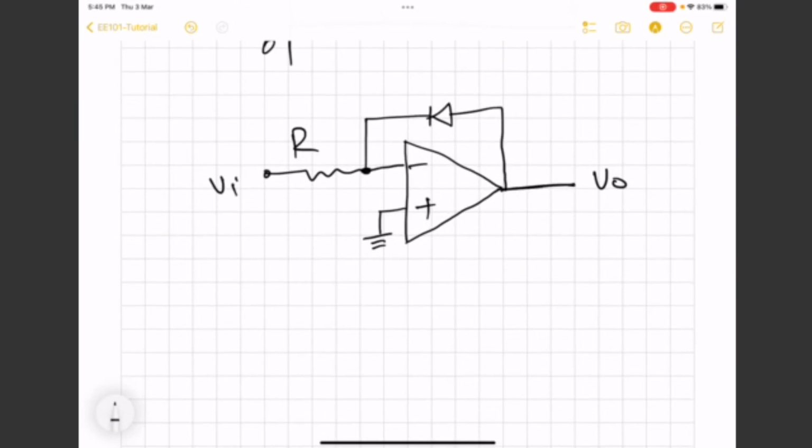So we will now try to find the voltage at this node X and at node Y. Here also the virtual short can be applied even if we have a diode in place of Z2. So keep in mind that Z2, or the negative feedback loop, simply implies that there is a possibility of current flowing between node X and node Y. That means output and V minus node.